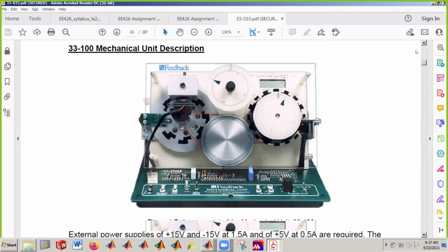One of these antennas that look up into the clouds, some kind of sensors or dishes that move around. So suppose this is the motor that drives this antenna. You may want to turn the motor a specific amount of angular deviation so that you stop at a specific angular position. So this is how you can think of this. This is just a motor driving, and it can actually drive any kind of equipment that you want. We can measure its angular position using this sensor, which will give you a voltage proportional to the position.